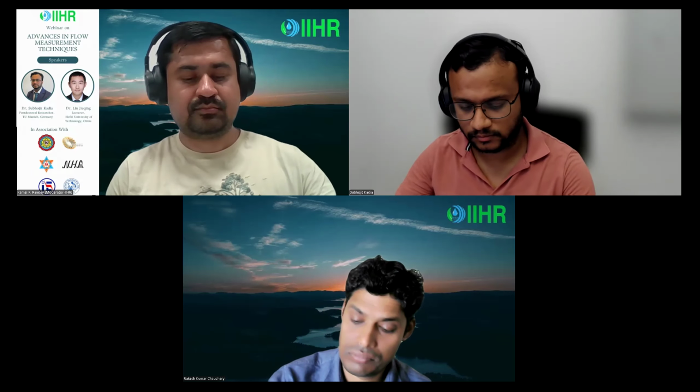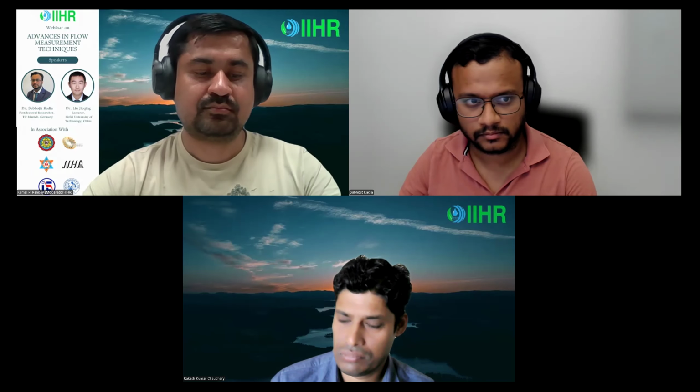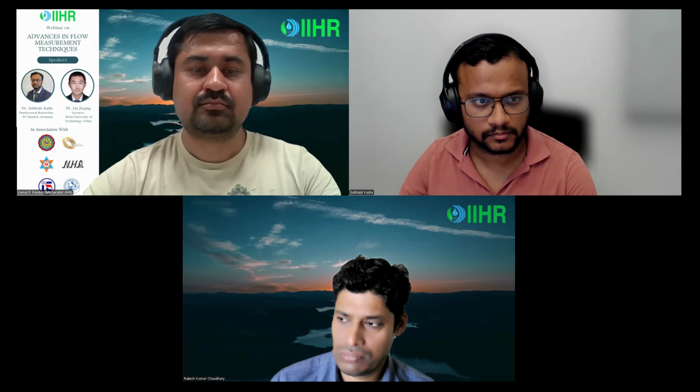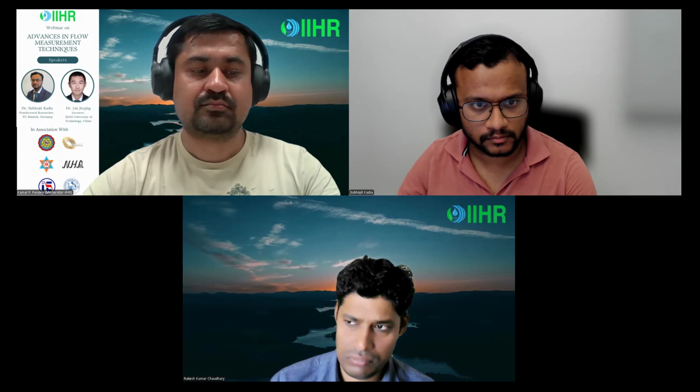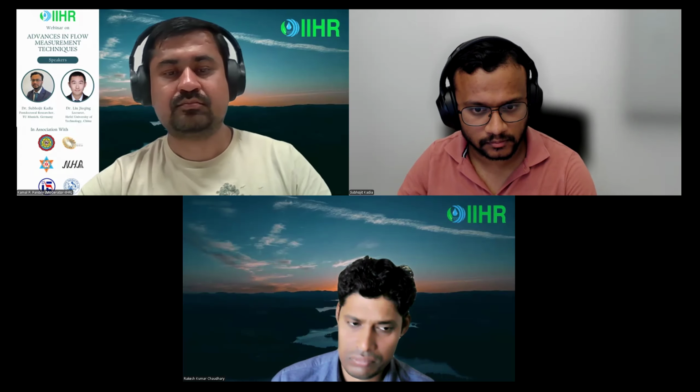And regarding the sediment, PIV and PTV is a source and maybe it takes some applicable formula. But currently we are using the acoustic backscattering system. It transmits different frequencies of sound, and then it will examine the reflection. So by evaluating the cloud density, we measure how much sediment concentration is there in the water.